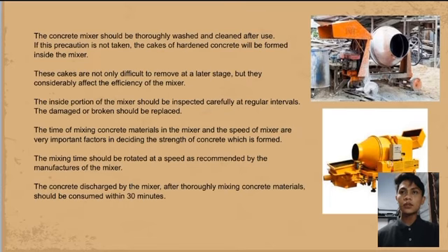The time of mixing concrete materials in the mixer and the speed of the mixer are very important factors in deciding the strength of the concrete which is formed. The mixer should be rotated at the speed recommended by the manufacturers of the mixer. The concrete discharged by the mixer after thoroughly mixing concrete materials should be consumed within 30 minutes.